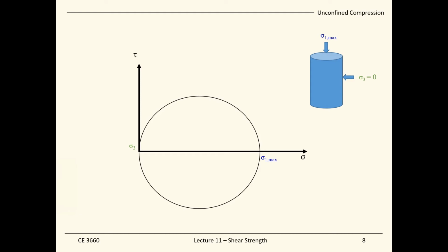The first stress point you can look at is the sigma 1 max. So we know a point, the sigma 1 max. And we also know the orientation, we know the plane, which is the horizontal. Sigma 1 is acting on the horizontal plane on the top of this specimen. So we know the plane and we know the point, so we can find the pole, which is right here. And we can double-check that with another available point and plane.